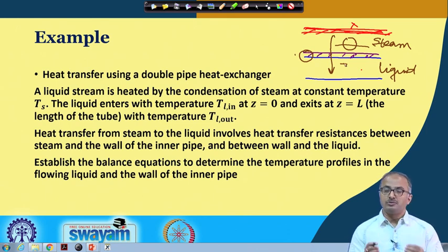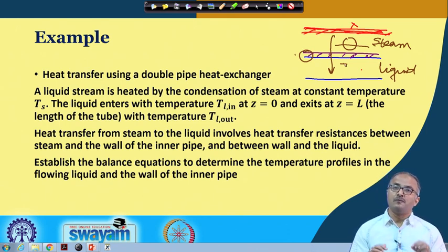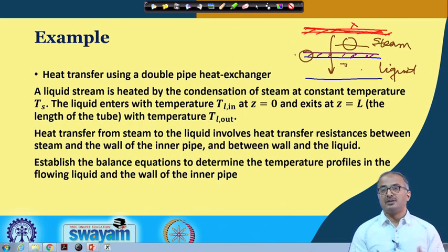Also we have to understand that we choose the material of construction of these tubes in such a manner that the wall has very low resistance, because we want the heat exchange to be effective. If the wall also offers a large resistance to heat transfer, then we would land up with a bigger heat exchanger.